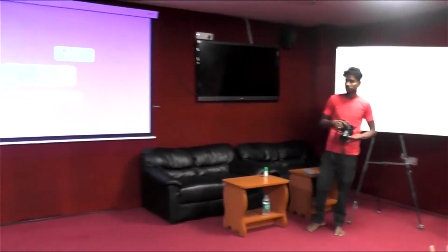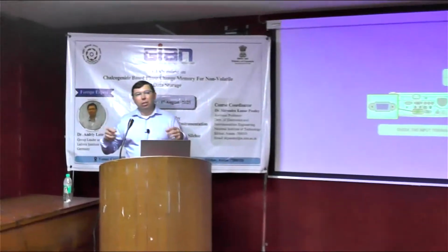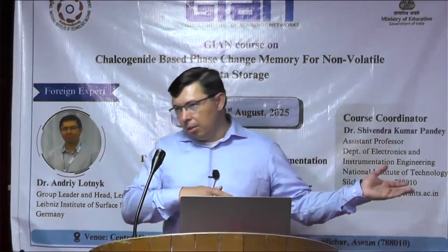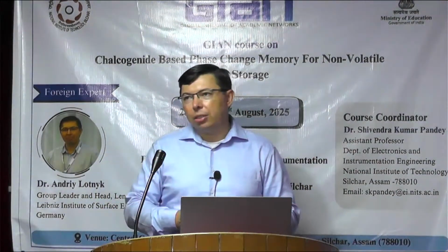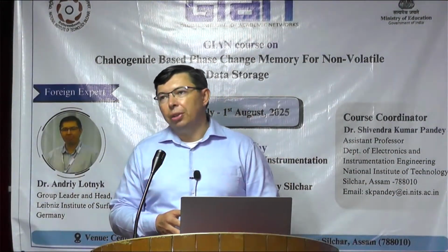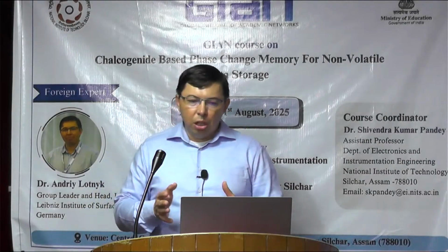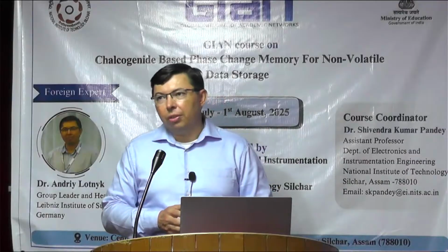Thank you. Sometimes if you think about photon measurements, you can go through this oxide layer, or you can think about how to etch a little bit and then deposit another contact. As I said, just use this deionized water. You can adjust your etching time, and then you can get a fresh surface. So it's a problem, but with fresh surfaces, you can somehow manage this problem. But this is a problem.